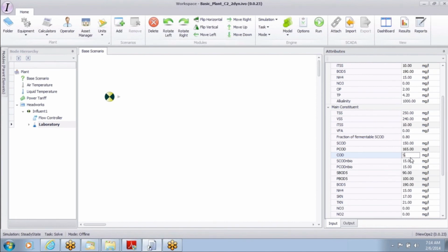But let's say our influent COD is 500. And let's say the soluble COD is 240. So it automatically computes the particulate COD over here, which is 260. These are the soluble non-biodegradable components, which come up through calibration and looking at your treatment system if you have an actual treatment plant. We don't have any data for now, just leave it around 10 or 15 unless your wastewater is much stronger or an industrial waste where it can be higher.